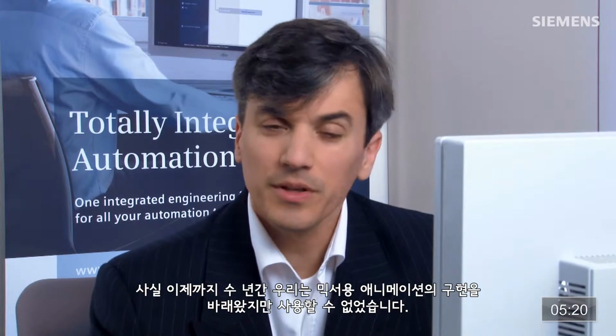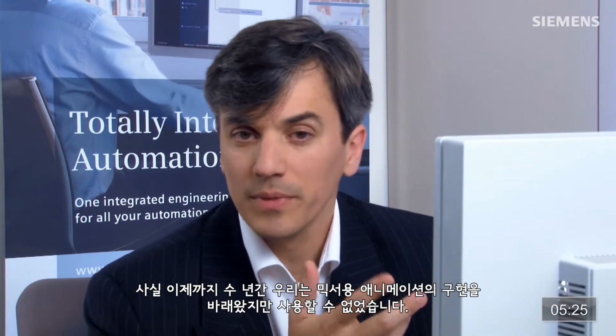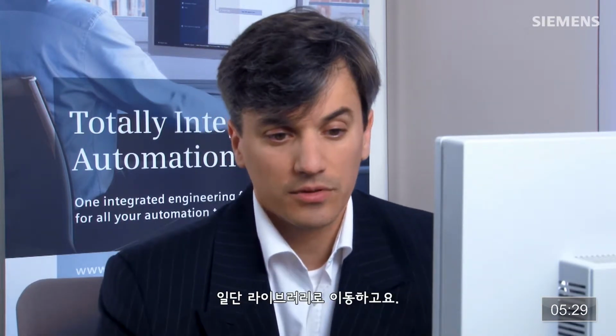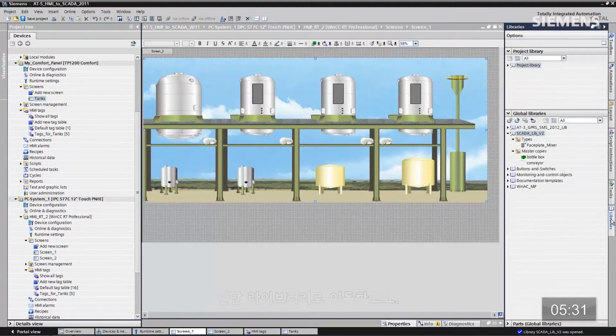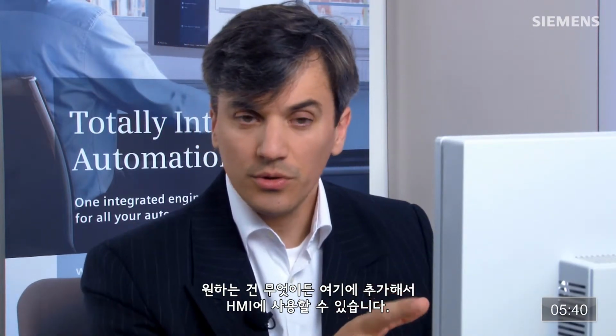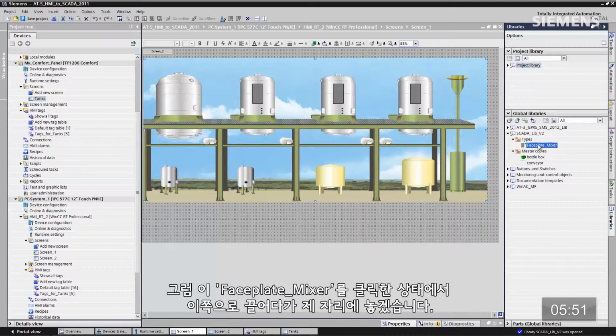Okay, so something that's been bothering us for a couple of years is we've always wanted to have animation for our mixer, but we've never had the opportunity or the time to do it. Now's the perfect time. So let me go over to our libraries, and I've got something called faceplate technology. So ultimately you could take graphics and animations, add them together for an HMI, whatever you want to do. Once you've got it exactly the way you want it, you can save that to your global library, and every single time you have a new panel come online, you go grab that faceplate, drag it on, and you're done. So let's go grab this faceplate for the mixer.